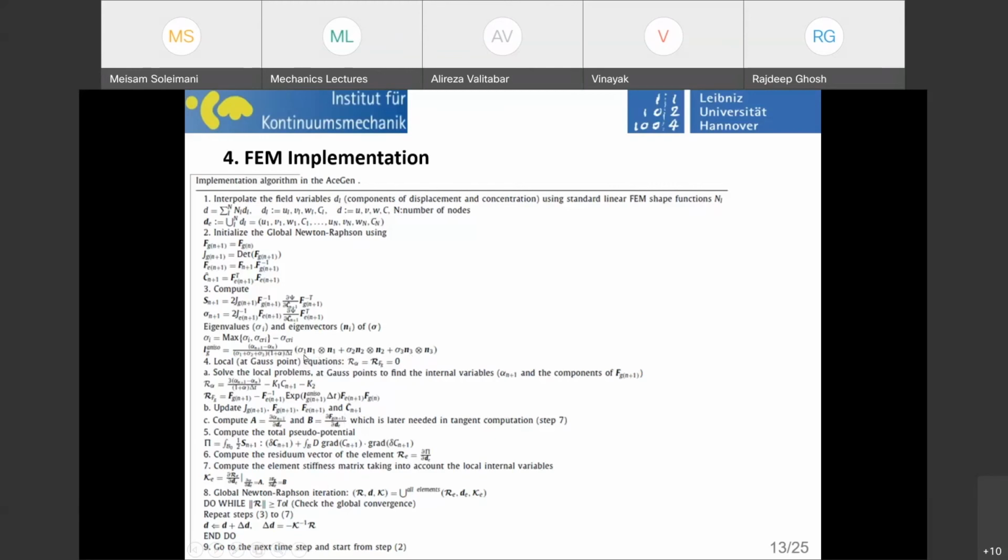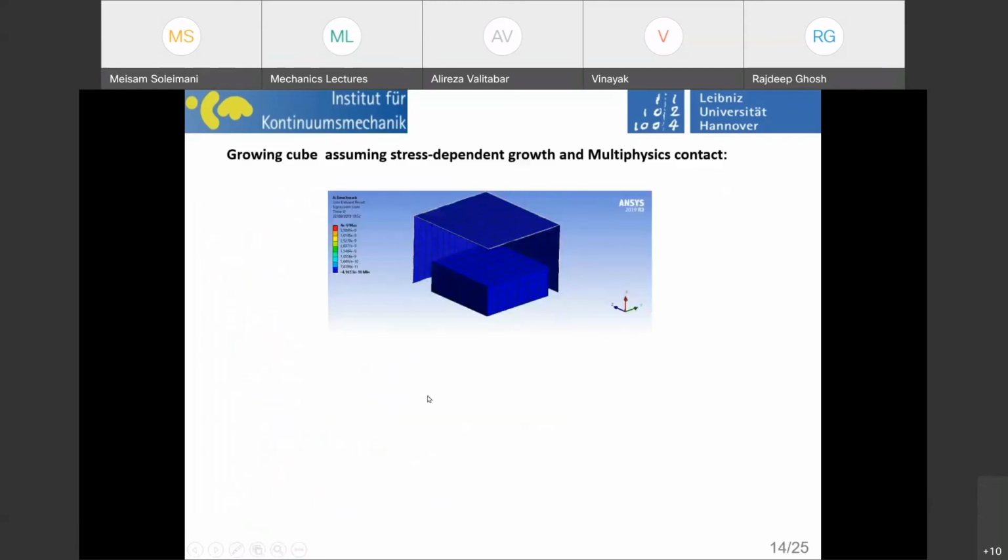Then after that, upon appearance of the contact, some of the directions are excluded from this L. And then once all of them reach that threshold, then L becomes 0 tensor. And then everything is frozen. So the growth is automatically stopped due to this feedback, because in the definition of the growth, we have not only that alpha, that is a function of concentration, but also it's a function of sigma. So keep in mind that in this model of the growth, we have 2 variables that the growth is a function of. The first one is the concentration, that you can assume is the driver of the growth. The second one is the stress, that is the controller of the growth. It controls how the growth is to be and where the growth is to be directed, and second, when the growth is to be stopped. Is it clear?